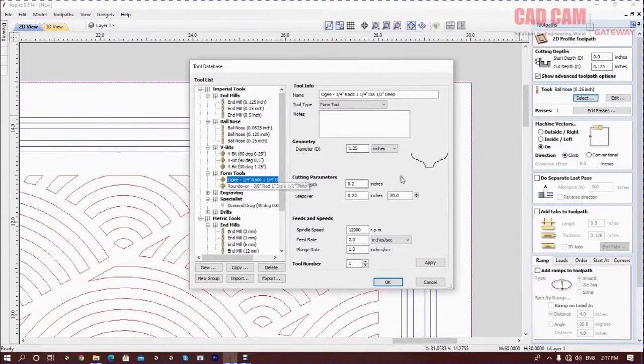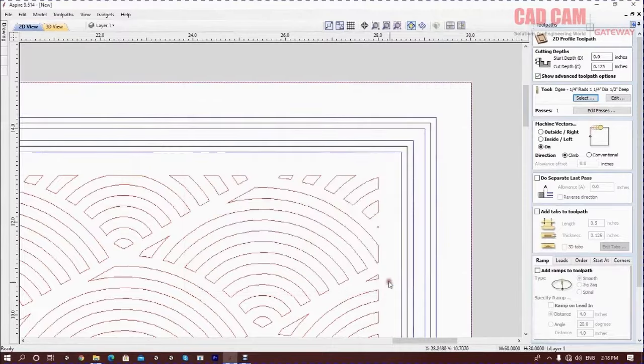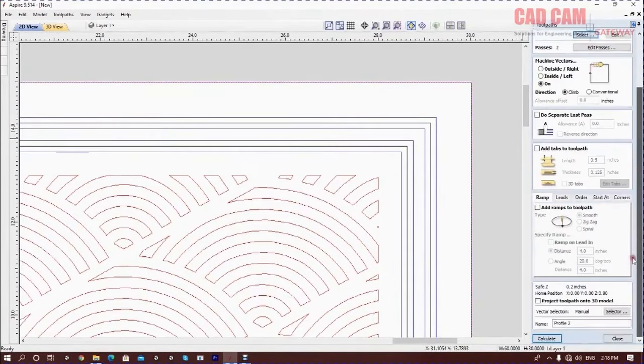And as for its round, I mentioned earlier that after selecting this tool, you will select this edge, the outer one, and you need to keep it as it is. You don't need to set it to outside or inside. You need to keep it as is. The pass has been set automatically. We will increase its depth, setting it to 0.25. Now the tool you have, you need to set it according to this.